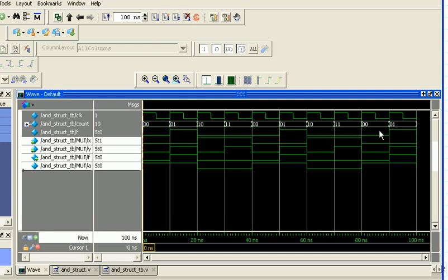And down here we have the same f, but from the actual module under test, whereas the upper one here came from the test bench, where we were actually getting that result back from the module under test. And we can also check that the A here, the output of the inverter, is correct. So that is the output of x. Here, the first 2 periods of the clock, x is 0, so the output has to be 1. For the next 2 periods of the clock, x is 1, so the output has to be 0, and so forth. So this is quite handy to actually see whether things were happening the right way.